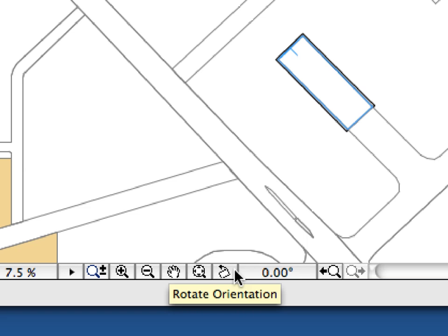We will use the Rotate Orientation feature of ArchiCAD to perform the necessary action. This enables us to temporarily rotate the project orientation of the floor plan. This way, we can rotate the axis of inclined directions with the horizontal and vertical directions to ease our work.